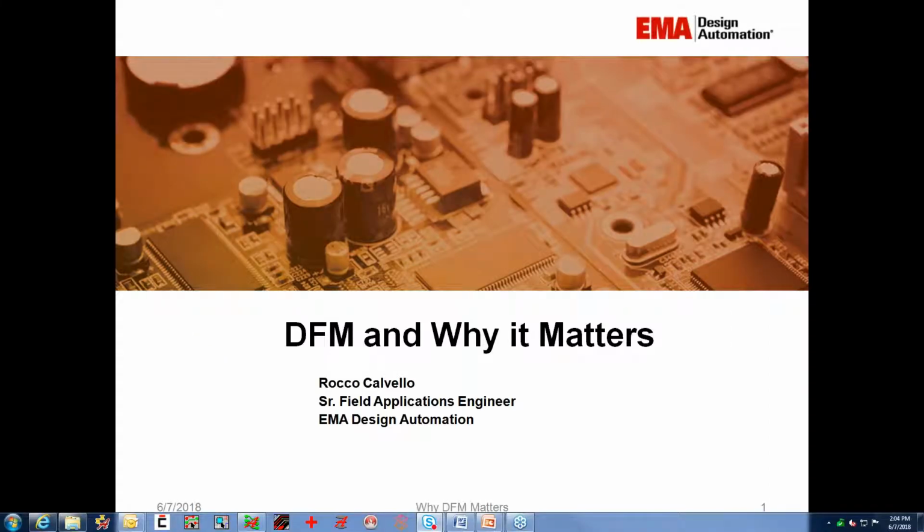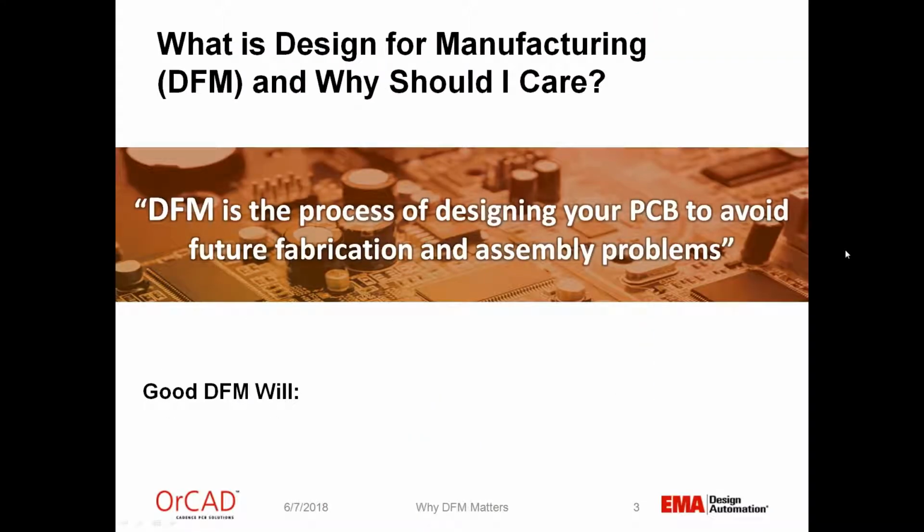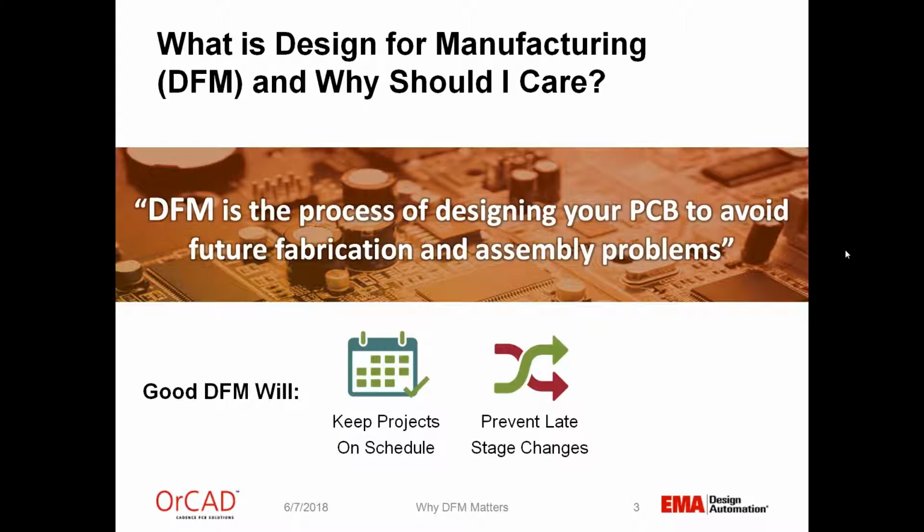All right, thank you. So good afternoon, everybody. Thanks for joining us today. I'm just going to go ahead and advance my slides here. So what is design for manufacturing? What we call DFM is the acronym, and why should I care? DFM is the process of designing your printed board to avoid fabrication and assembly problems. And a good DFM will keep your projects on schedule, prevent any late stage changes in the design, and keep your build costs predictable.